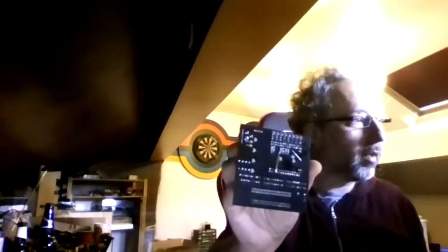So I've bodged it with a piece of braid from one to the other to decrease the impedance. Yeah. Would it have been better to just put more wires between those 2? So I think there's a bit of bounce coming from the bottom plane going to the top plane and back to the bottom plane. I just put 1 wire in for each transition. If I put like half a dozen, would that have probably improved things?